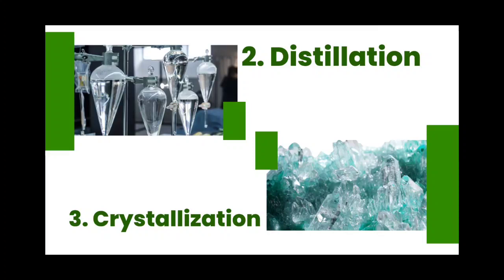Operating conditions include cooling rate, which affects crystal size and purity. Supersaturation, achieved by dissolving more solute than the solvent can normally hold at a specific temperature, is essential for crystal formation. Stirring or seeding: seeding the solution with existing crystals provides nucleation sites, encouraging crystal growth.